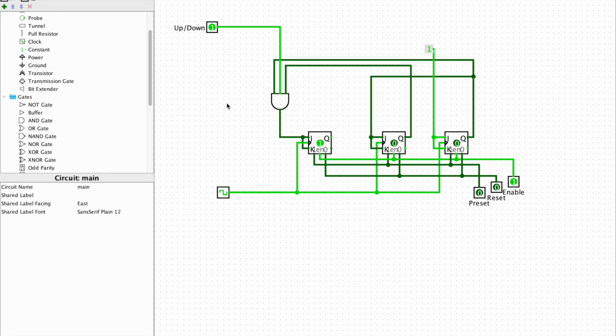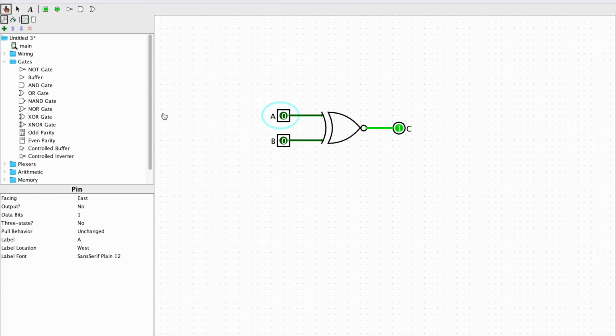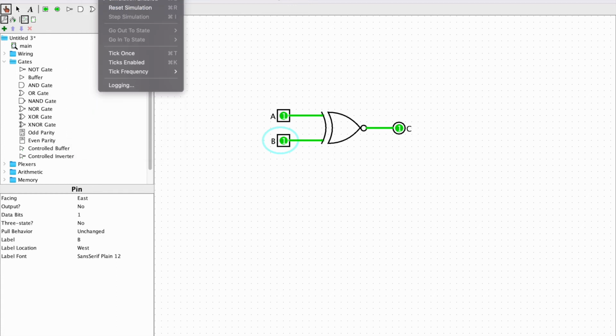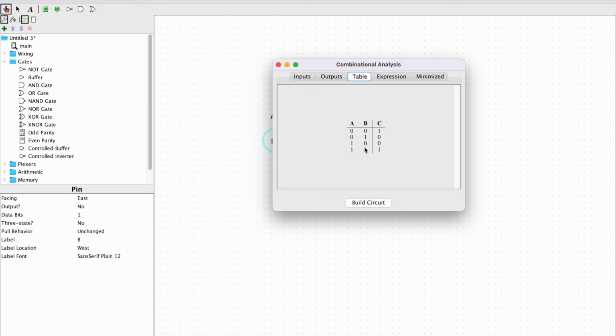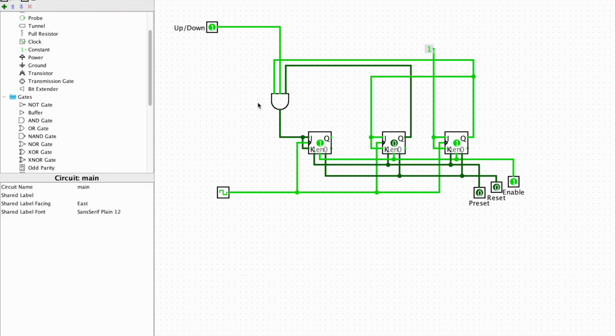So there is this gate called XNOR gate which does exactly what we want, which outputs the value 1 for the combination 0 0 and 1 1. For no other combination does it output the value 1. So here you can see for 0 0 we are getting 1, and for 1 1 we are getting 1. So we'll use this XNOR gate in our circuit.